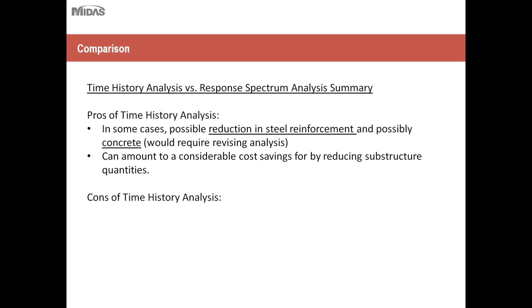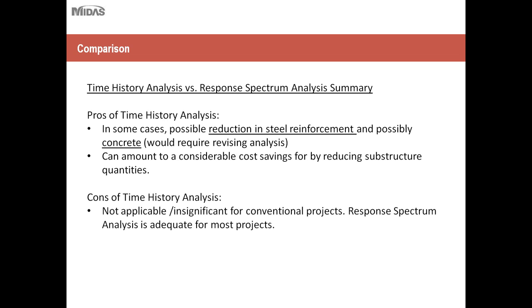And then the cons of time history analysis. First, it's not applicable or it's insignificant for conventional projects. So for those of you who are working in low seismic regions, very rarely will you ever need to use time history analysis, if at all. So for the most part, you'll be sticking to response spectrum analysis because it's not as optimal, but it requires much less effort and it's adequate for most conventional projects.